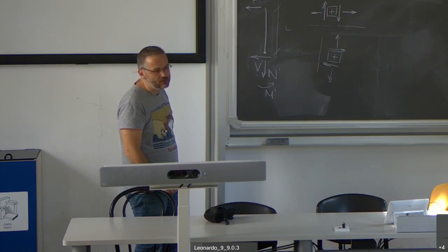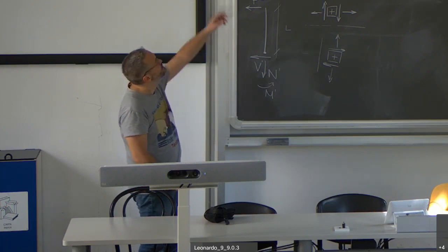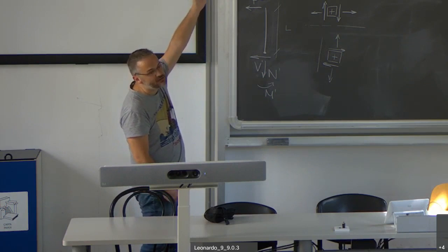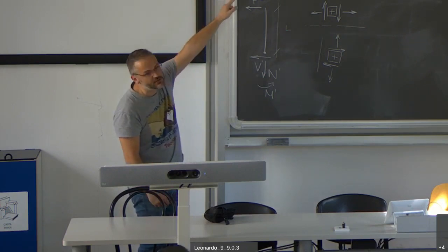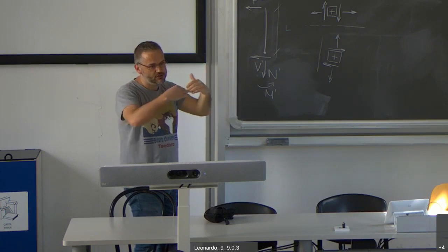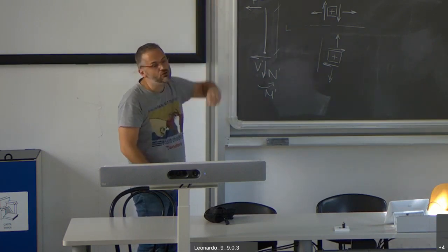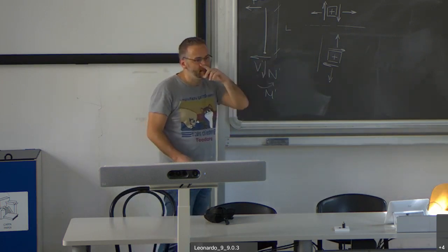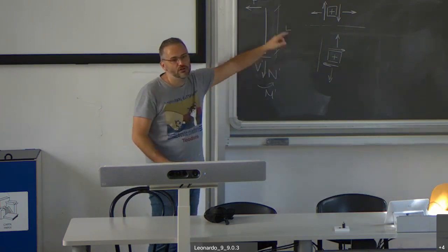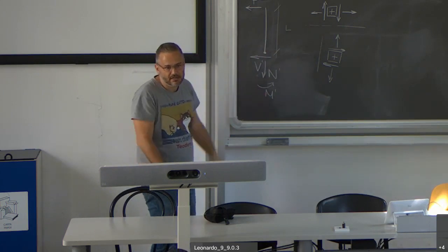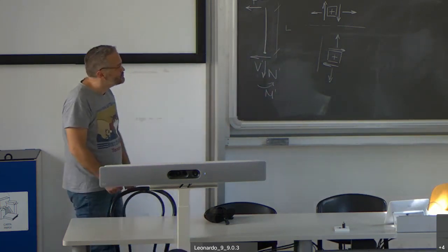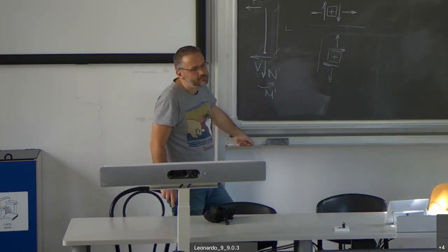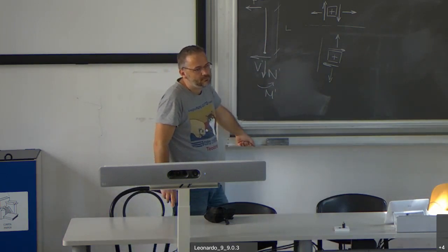Not right now. As I said, if you look at the left part of the structure, until you get to the center point where all the 3 portions get together, I don't need to know the reaction forces. And I dare you to prove me wrong: will I need to use the internal forces in this calculation? Clearly not. We're writing these to acknowledge that these forces and limitations exist on that point. But for now, we don't need to know their value.